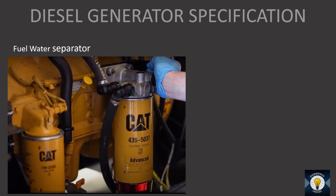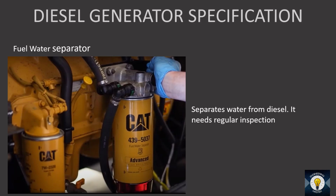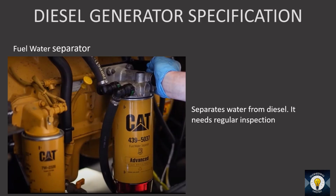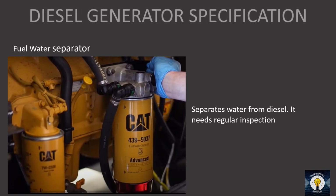Fuel water separator, what is it doing? It will separate water from diesel. So the fuel water separator separates water from diesel and sends only pure fuel to the engine. This separator needs regular inspection. The trapped water has to be removed frequently.